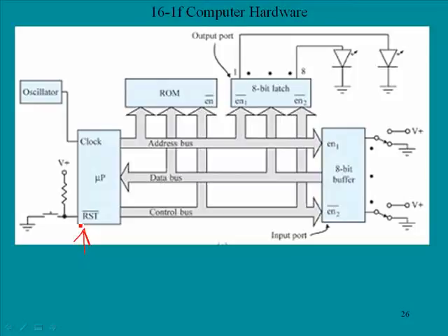The instant we press the button, the wildly uncontrollable activity ceases, and the program counter goes to 000, and this is our hex address, and it stays there. When we release the reset button, the desired controlled program execution begins. Okay? It will progress as outlined in the following paragraphs. Okay, so we have a program that's stored in ROM, and we're going to begin to execute it starting at memory location 0000.